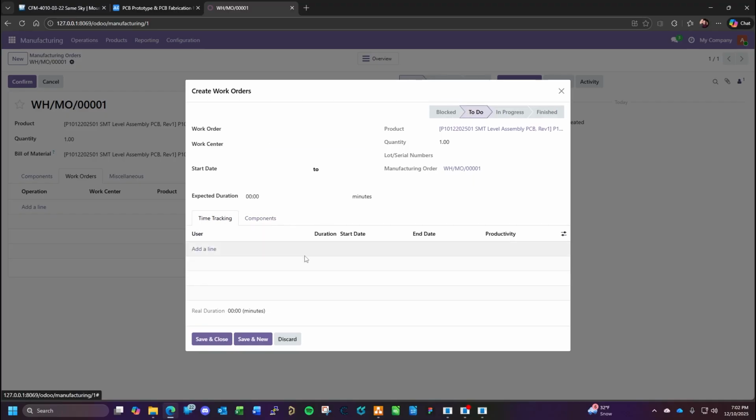expected duration. So the cool thing is you can use this to start doing time studies. And that's great for planning, resource allocation. I've had to do a bunch of time studies in the past at other places I've worked. It's essentially taking a process and using a stopwatch and figuring out how long it takes somebody to do a specific task. And you try to average that and figure out an optimal time based off of what your technicians can actually do. And then this can help with resource planning and allocation.